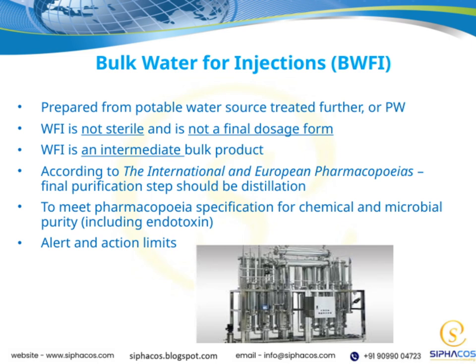According to the international and European pharmacopoeias, the final purification step for WFI should be distillation. This step is critical to ensure the water meets the necessary standards for chemical and microbial purity, including endotoxin levels. We also need to be aware of alert and action limits.